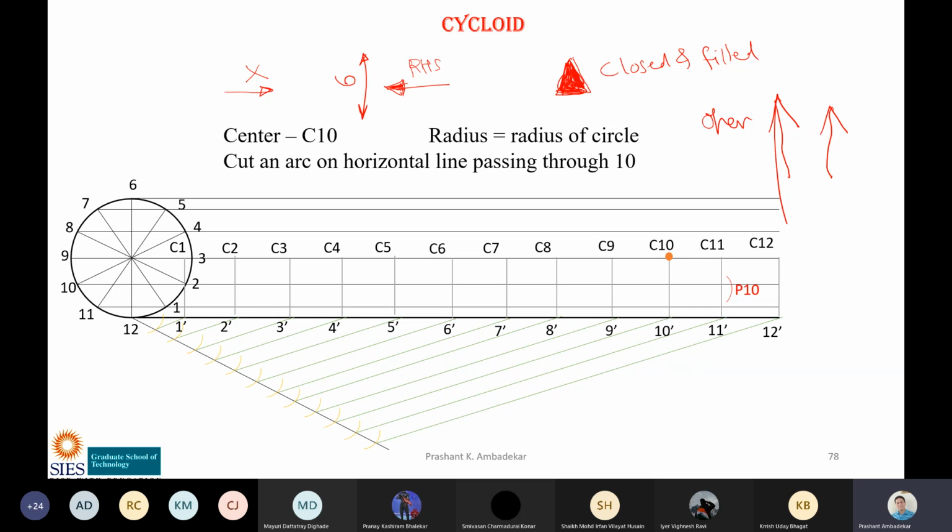Now another thing to be remembered about the arrow is this distance to this distance. If this is 1 mm, this should be 3 mm. So the ratio is 1 is to 3. If this is 2 mm, this should be 6 mm. So the ratio is 1 is to 3. Now again a question from your end, sir. Will they count every time they draw how much the arrow is? No, no need to do that. You draw the arrow in the ratio 1 by 3.